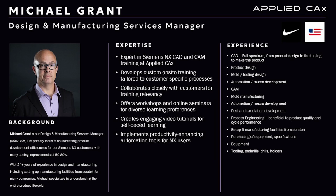I've got 25 years experience in manufacturing and design, and a somewhat unique background in that I've set up facilities from scratch. Where that kind of started was, I was working for an injection molder back in the 90s, and it started with noticing that the process was wrong. They were running a part, and it was running 200 degrees Fahrenheit over temp, and I was like, hey, something's wrong there, so I dug in and fixed that. It had to do with the flow channels and the gates and the runners, and it was fixed, ran at the right temp.